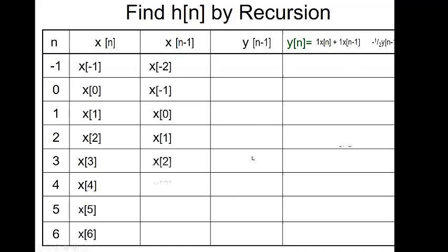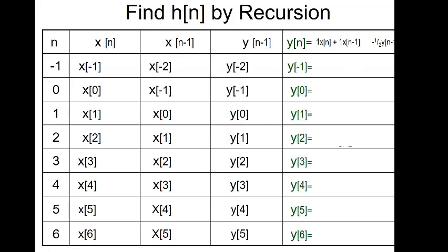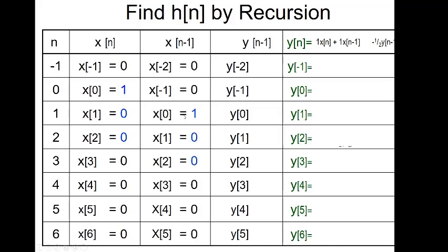The setup is still the same, and again, you don't have to put in all these indices. We put in our unit sample sequence for x sub n, 1 at n equals 0, and 0 everywhere else for that column. x sub n minus 1 looks just like in the previous time. We'll take the 1 and shift it down to n equals 1 and put zeros everywhere else.